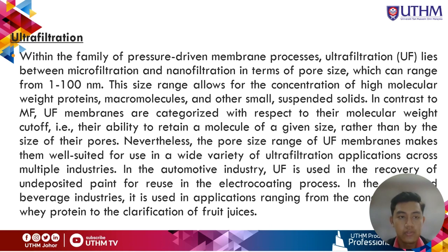In contrast to MF, ultrafiltration membranes are categorized with respect to their molecular weight cutoff, their ability to retain a molecule of a given size, rather than by the size of their pores. Nevertheless, the pore size range of ultrafiltration membranes makes them well suited for use in a wide variety of ultrafiltration applications across multiple industries.